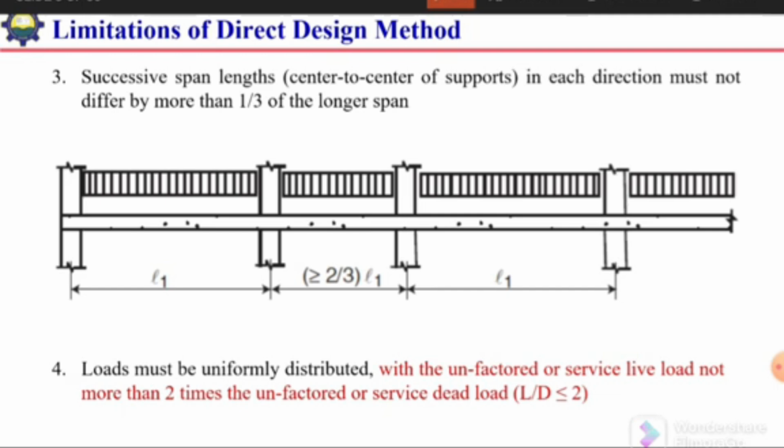So this might be confusing, that in case of slab system sometimes we have walls on it, so that is not a uniformly distributed load, that is a line load. So if the line load is on the beam underneath the slab, then it is okay. But within the panel, there should not be any point load or line load.